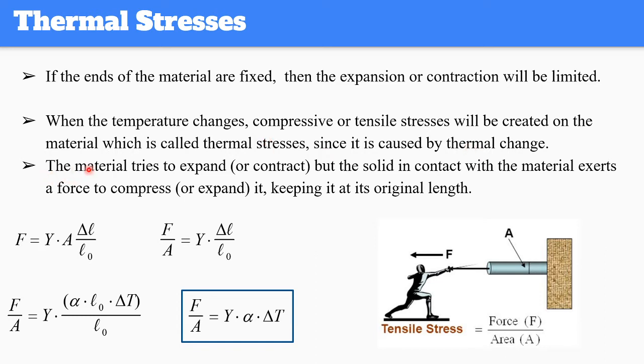The material is trying to expand, but the solids in contact with it exert a force to compress it, to be able to keep the original length the same. So think that this is blocked from both sides. Once you increase the temperature, it's not going to be able to expand, and it's just going to create some force.